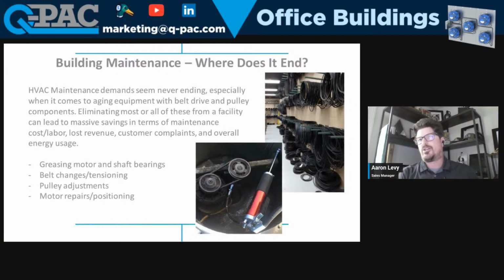When you're looking at a lot of old existing systems with belt drives, direct drive plenum fans, vane axials, things like that, where they've got direct drive motors or belts or pulleys, there's always some kind of servicing that needs to be done, bearings to be greased, belts to be changed, motor tension bases need to be adjusted on the regular. These things eat up a lot of maintenance time.